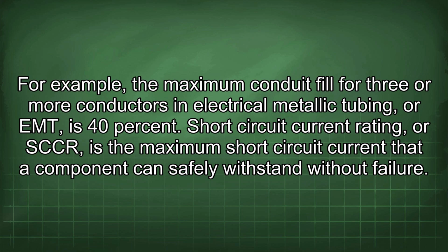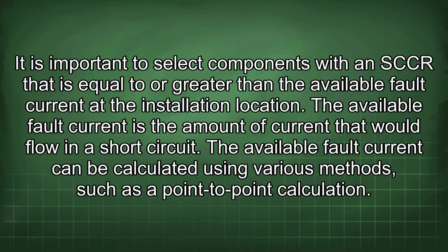Short circuit current rating, or SCCR, is the maximum short circuit current that a component can safely withstand without failure. It is important to select components with an SCCR that is equal to or greater than the available fault current at the installation location. The available fault current is the amount of current that would flow in a short circuit. The available fault current can be calculated using various methods, such as the point-to-point calculation.